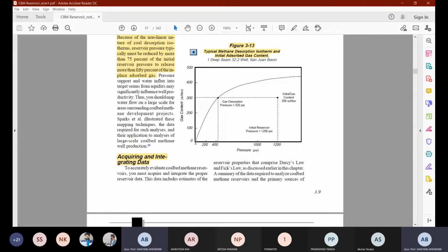Okay, but this 1.5% moisture, as you have dried the sample under 110 degrees centigrade for two consecutive days, okay, this is the standard process in the closed chamber. Even if you dry the sample to constant weight, you will never see that the moisture is 0%. If the moisture is 0%, that is also dictated by the coal structure.